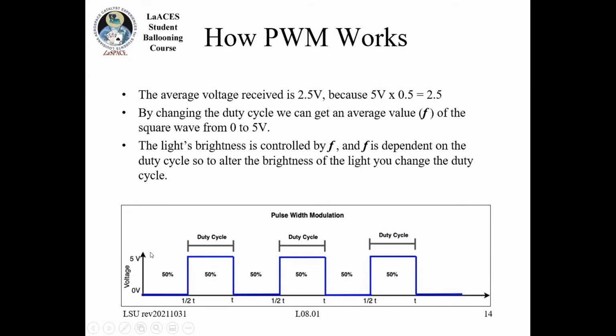And it turns out you can pretty easily put some kind of averaging circuit, consisting of a couple of capacitors and resistors, on the output, and it will smooth out that average.